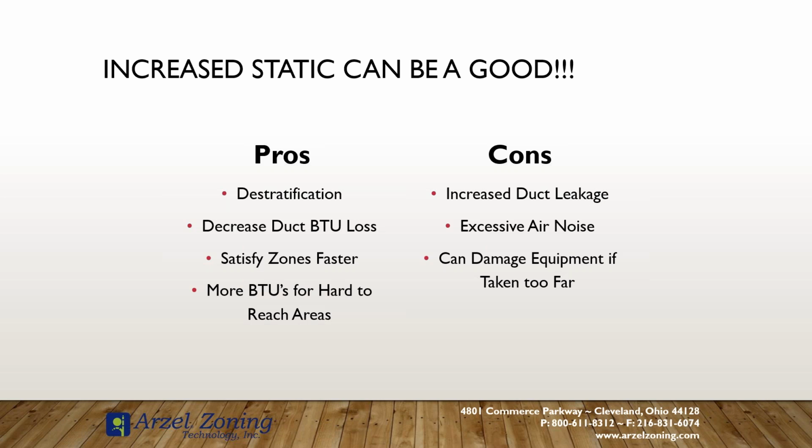It can cause excessive airflow noise. So the higher we push that static, the more feet per minute we have coming through our register, the greater likelihood is that we may run into a whistle, and that's going to cause nuisance issues for our customer. And then it can be damaging on the equipment if we take it too far.